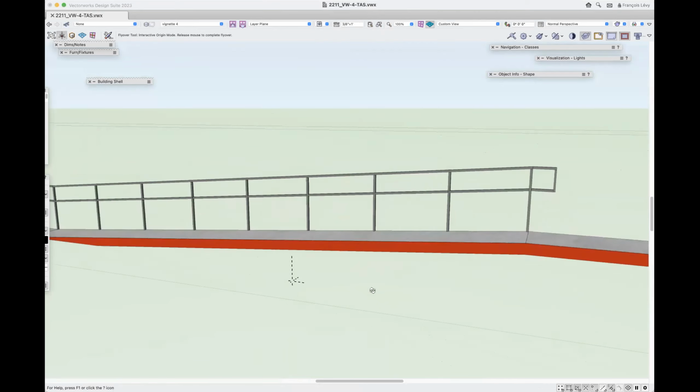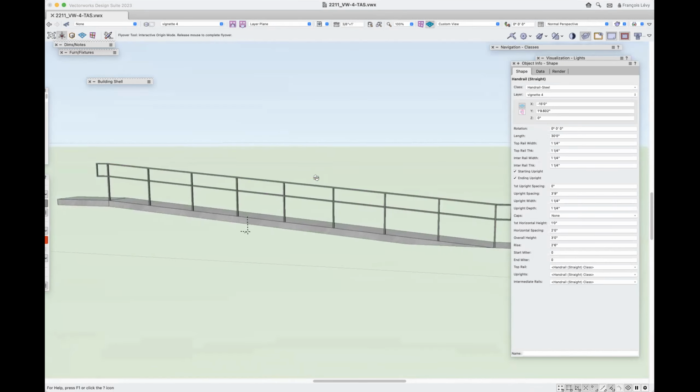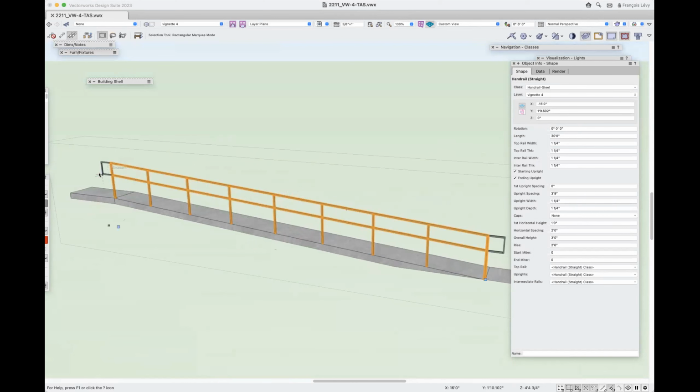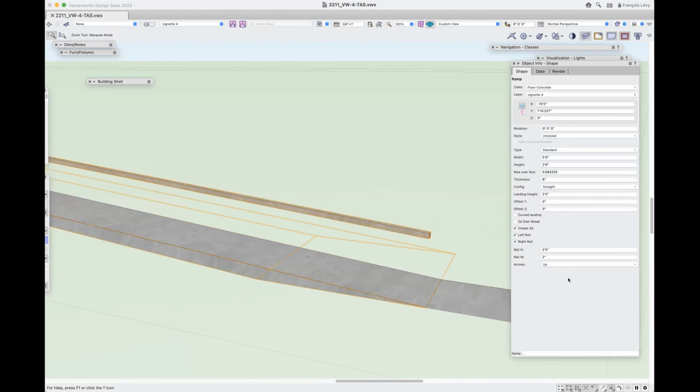And so this is the ramp itself that I've just highlighted. Then I've just added floors at the end for the landings, just to have a little bit more control. It's not integral to the ramp itself. I'm going to go ahead and delete this handrail and turn on the ramp's handrail. You can see that the ramp's handrail is a literal handrail. It assumes that it's going to be mounted to the wall. It doesn't really do much for me, right? So